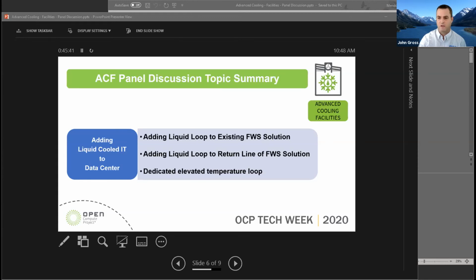One of the other colleagues that Valley and I have on TC99 is one of the head engineers for one of the storage hardware manufacturers. And I had this specific conversation with him when I was doing the work on the immersion. Basically what he said is that once you cross about 45C or so, and you start going above that, you start seeing more faults on drives, whether it's an SSD or a hermetically sealed spinning drive.